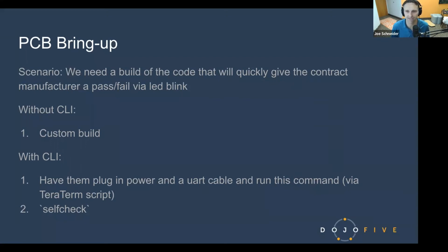So, the really common thing. Endless possibilities. I've seen it as easy as an IO pin's boot up state being grounded or pulled high. Sure. I'm going to jump into interfaces later, but a big one is, when I say JTAG, I mean Segger RTT, which is also usable by PyOCD now. You have JTAG, but you also have a UART, an ASCII interface there. And actually, when we talk about the first time I implemented the CLI that we chose, I used RTT.